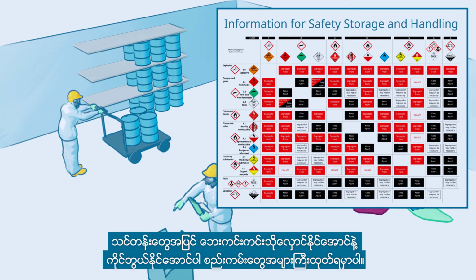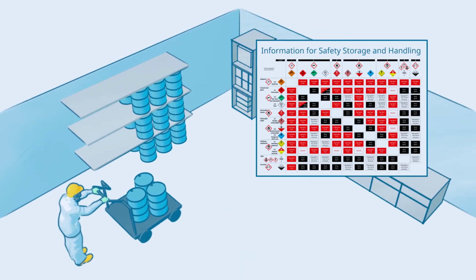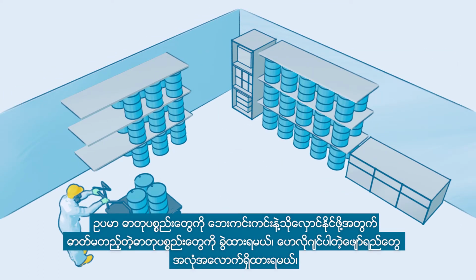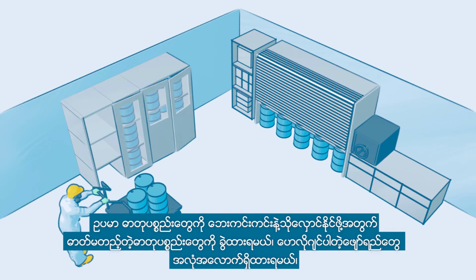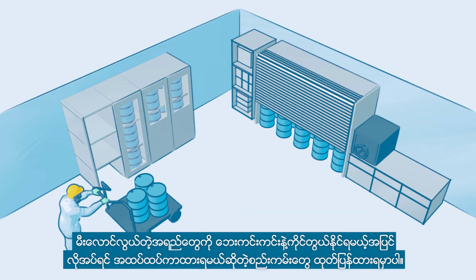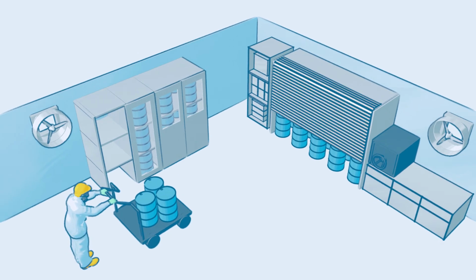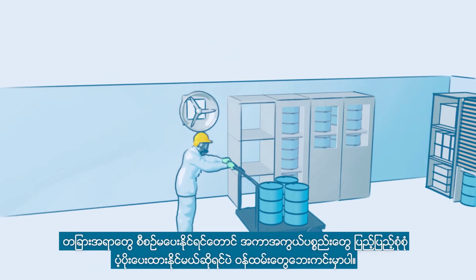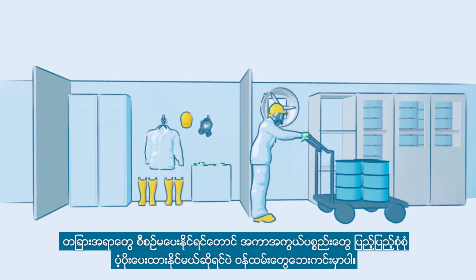In addition to training, a number of provisions may be necessary to guarantee safe storage and handling. For example, for safe storage of chemicals, there should be provisions for separation of incompatible chemicals, adequate storage of halogenated solvents, adequate storage of flammable liquids, and secondary containments. Engineering controls such as ventilation will help to contain and reduce the release of chemicals into the workplace. In addition, the provision of adequate personal protective equipment will safeguard the workers when other controls are not feasible.